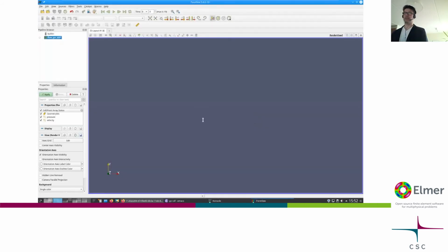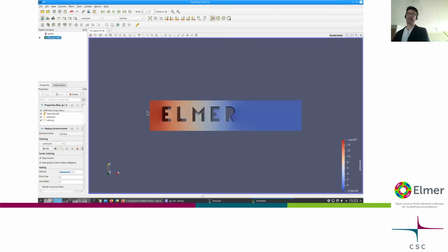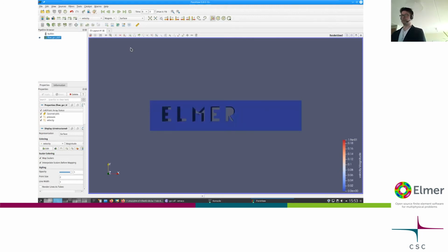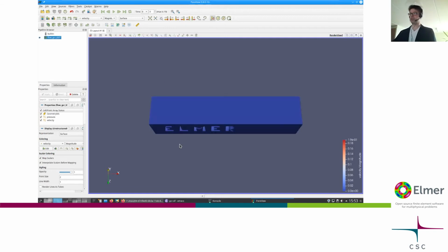Press OK. And then people often think, okay, what's happening? I can't see anything. ParaView demands you to press the green Apply button, and then you will be provided with a picture of, in this case, our Elmer mesh, already with a variable displayed. I guess it's simply the first one that's available. The pressure, or you could have the velocity, which in this case wouldn't bring you pretty far, because as you can see, we have no-slip conditions all over the place on the boundaries.